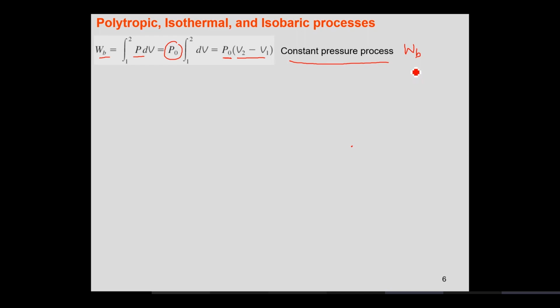यस सर। All right. Now the expansion and compression of gas are normally expressed by a generic equation which is PV to the power n equals constant. This is known as a polytropic process. Generally, the expansion and compression of gases follow this relationship, where n and C would determine the path.